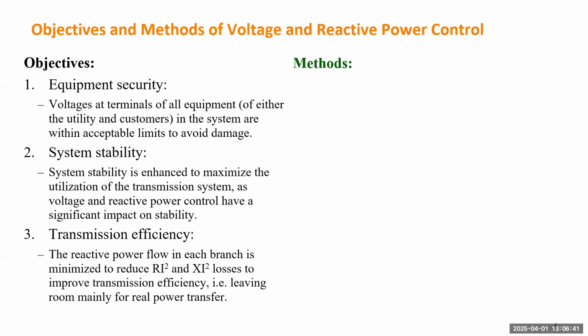The third objective will be the transmission efficiency. If you can design how the reactive power is dispatched and provided within the network, you can minimize the current along some long transmission lines, and as such you can reduce the transmission loss.